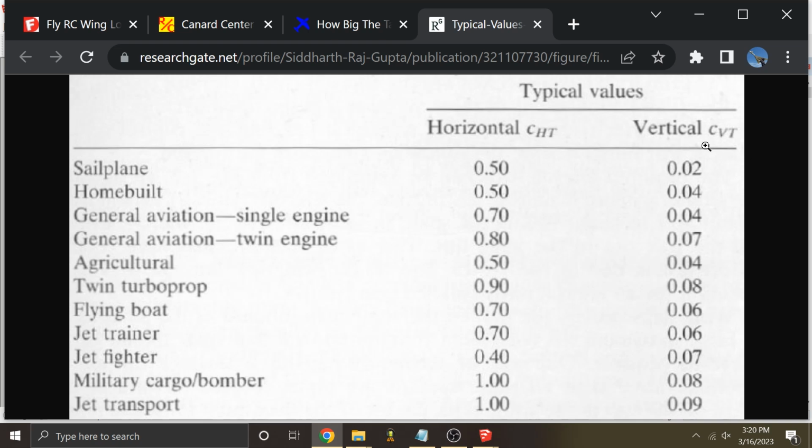I also want to consider that we're going to be in high alpha, and when you're in high alpha, your elevons won't do much in terms of rolling the aircraft. Mostly it'll be done by yaw. So we will have thrust vectoring to help it out, but I still would like to oversize the rudder just to help out with controlling the aircraft at high angles of attack. So we'll probably shoot for around 0.03, 0.04.